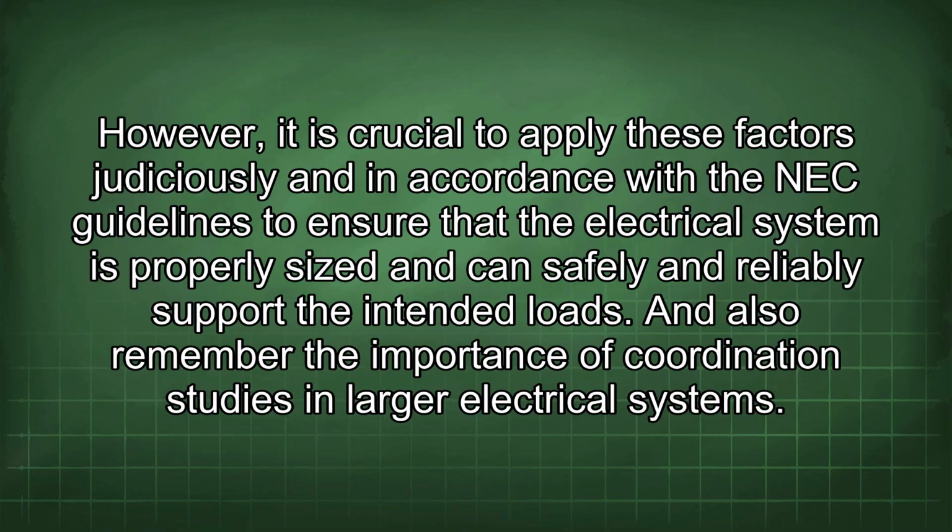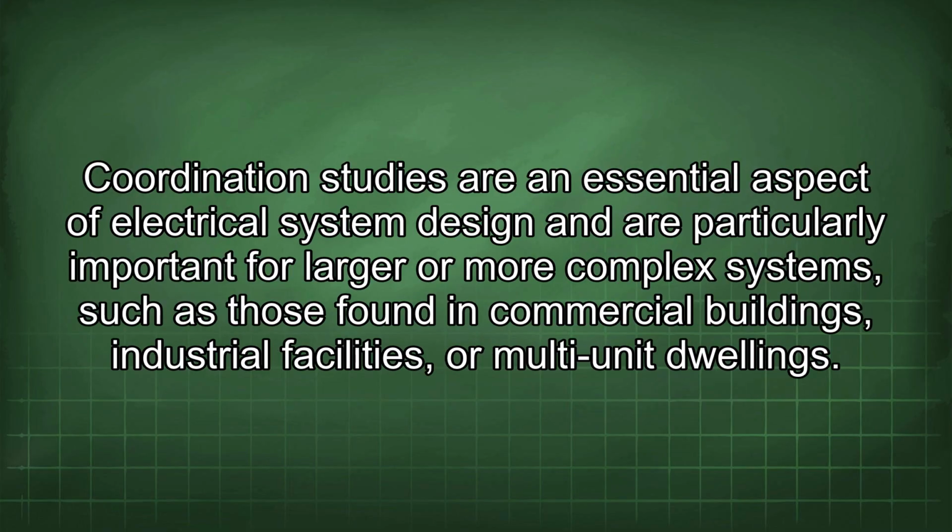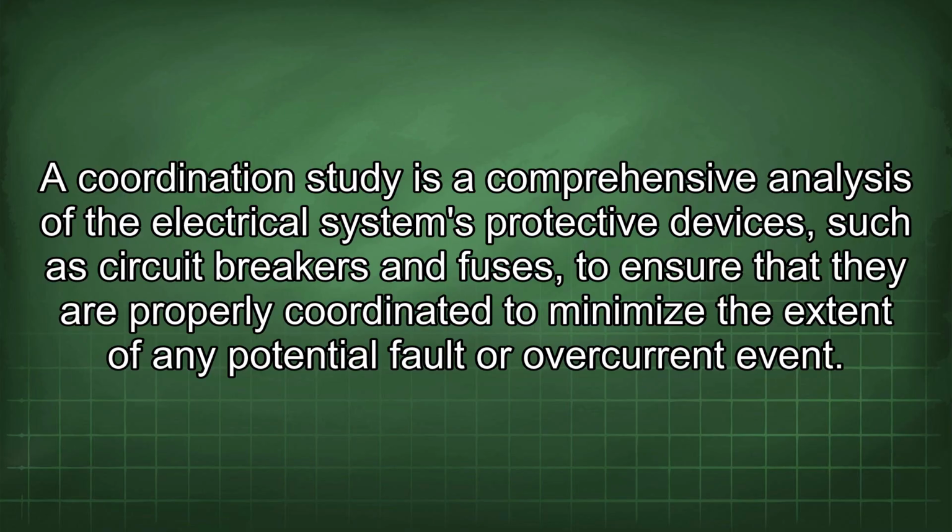And also remember the importance of coordination studies in larger electrical systems. Coordination studies are an essential aspect of electrical system design and are particularly important for larger or more complex systems, such as those found in commercial buildings, industrial facilities, or multi-unit dwellings. A coordination study is a comprehensive analysis of the electrical system's protective devices, such as circuit breakers and fuses, to ensure that they are properly coordinated to minimize the extent of any potential fault or overcurrent event.